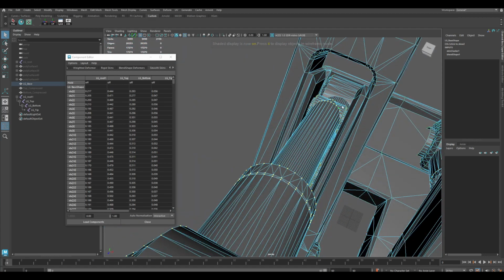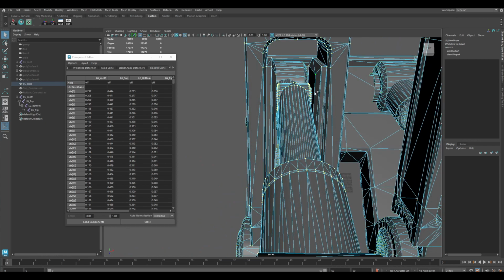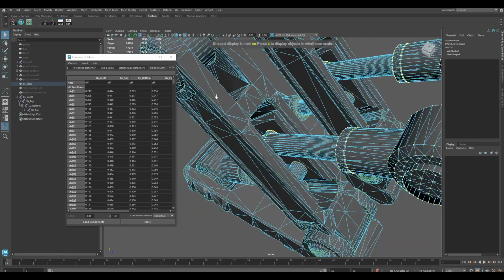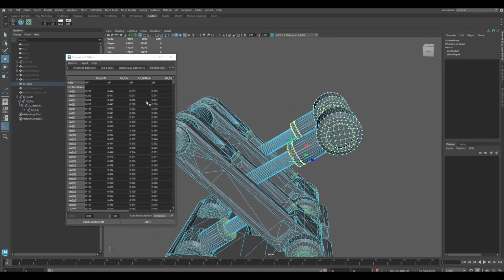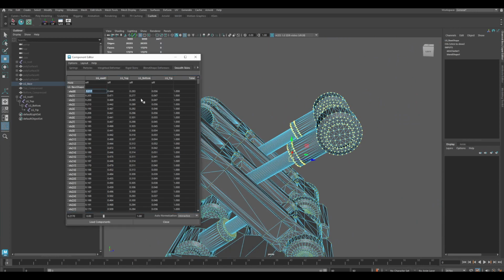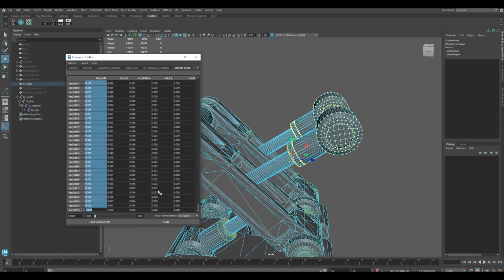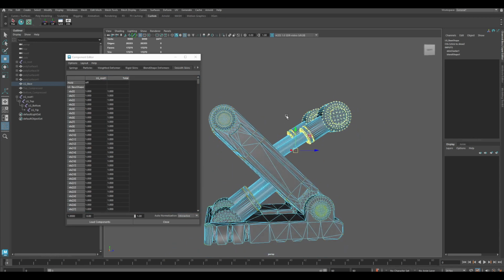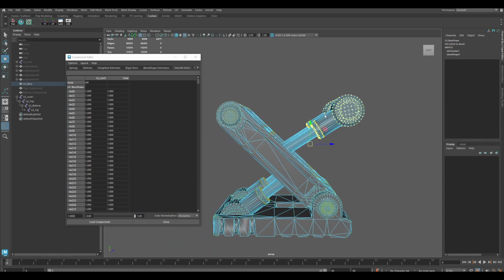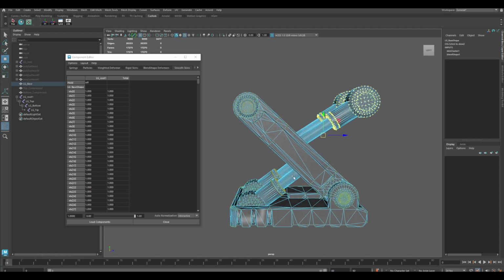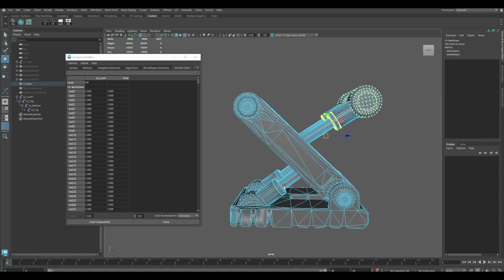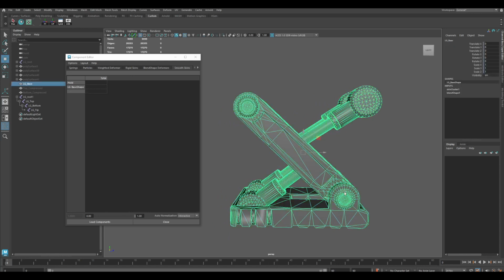We'll have everything here parented to the root bone. All our parts of the top suspension, we'll do them fully controlled by the root bone. That's because we don't want this part to move when we move our top suspension or our bottom suspension. We want it just to compress with our morph target, and the bottom suspension will actually move with our top arm and will compress based on our morph target.